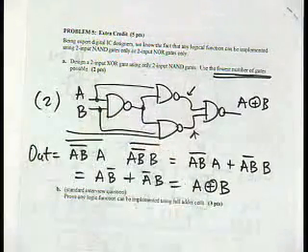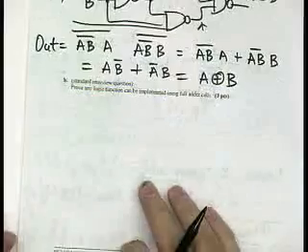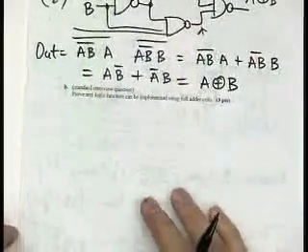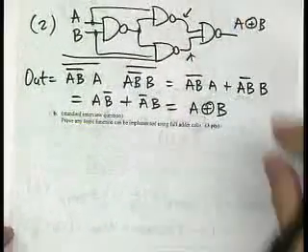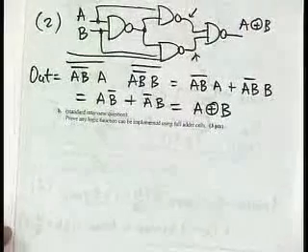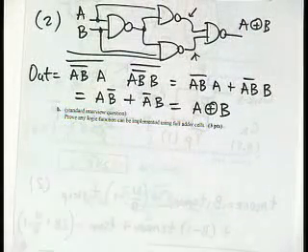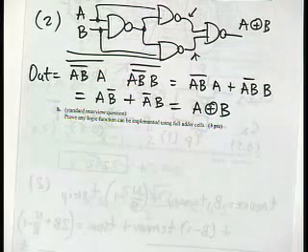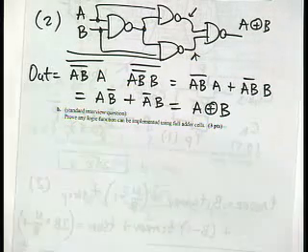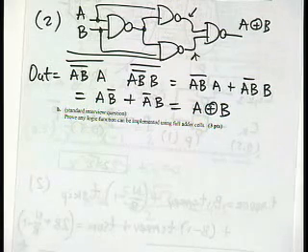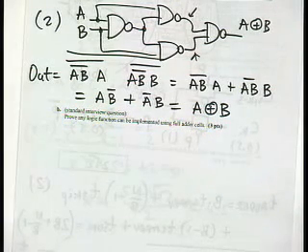If you didn't, 0. So the second question was then prove that any logic function can be implemented using full adder cells. So what you needed to do there is basically figure out what is the way I can implement either 2-input NAND or 2-input NOR using full adder cells. If I can implement a base function, I can implement anything, right? So that's the basic idea.